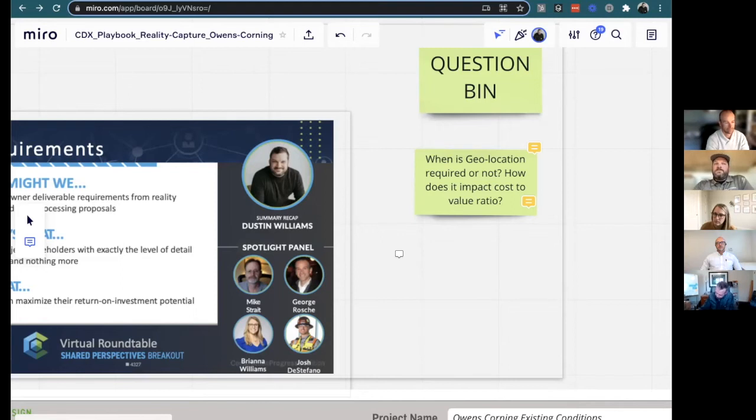And typically everything we do will pick a benchmark within the building. We will call that 000. And that's how everybody designs. That 000 may carry a coordinate that I can actually reference back in the geospace and say, yep, the 000 point of this building is at X latitude, X longitude, and X elevation.